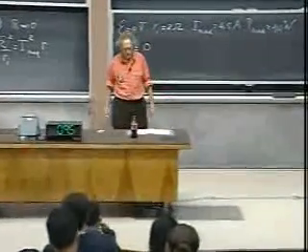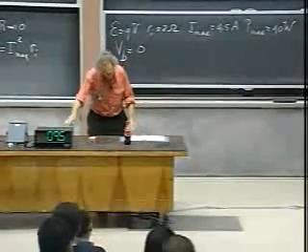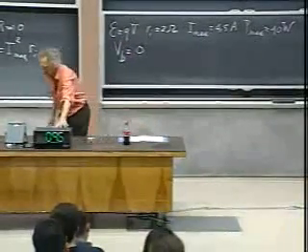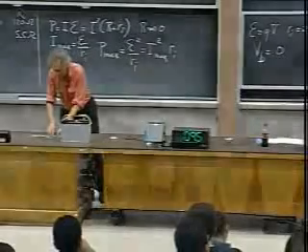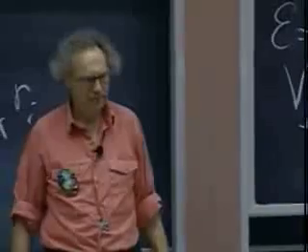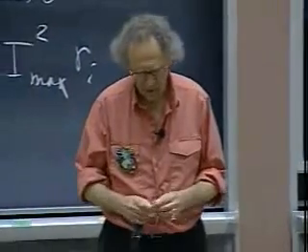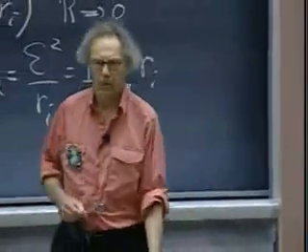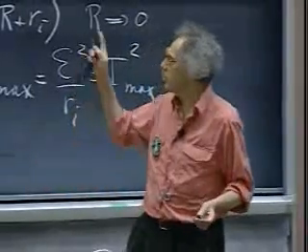So let's do it. I have here the voltage that you can see that we measure, a 9-volt Duracell battery. You can read it here. I hope the decimal point is in there, but it's about 9.6 volts. And now I'm going to do something stupid, but again, it's not dangerous. I'm going to take my car keys and I'm going to short out the battery. So simply connect point A with point B.